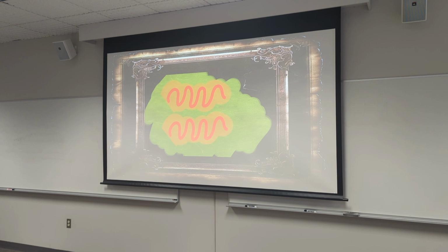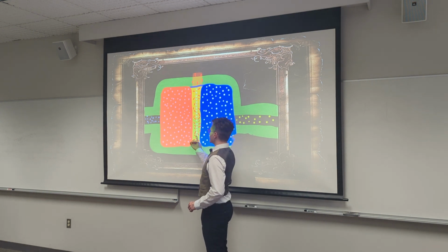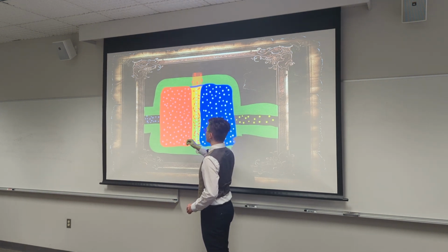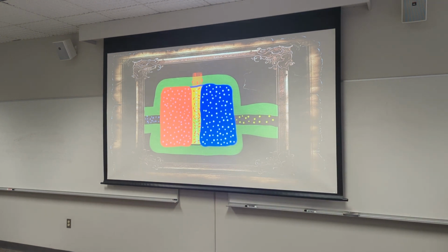And so what happens is, now those two will go and they will excite more electrons, or bump into excited electrons, which will release more coherent photons. And this process is repeated over and over again. And we get a steady stream of coherent photons that are all basically identical to each other. And it's designed in such a way that the photons traveling along this axis will hit more filled charge carriers and release more coherent photons. And the result is that we get a beam of coherent photons leaving that diode, which we call a laser.